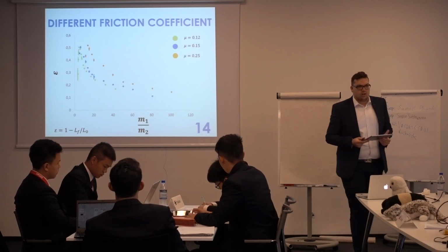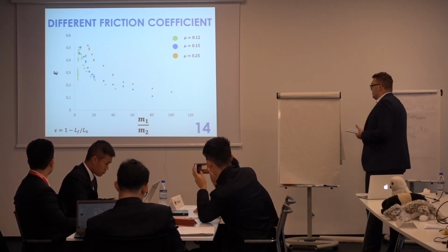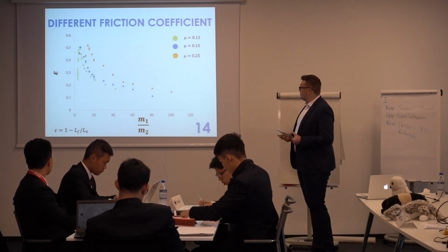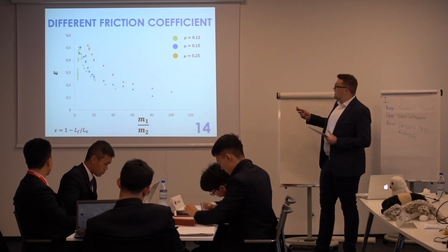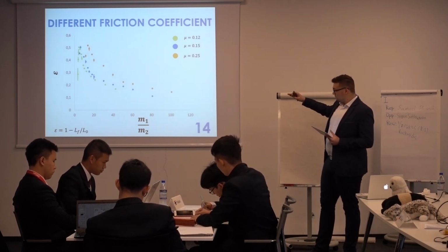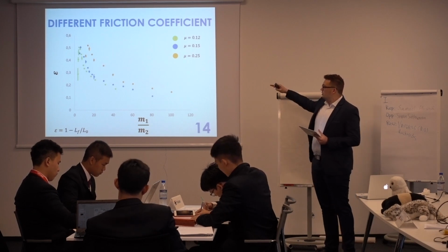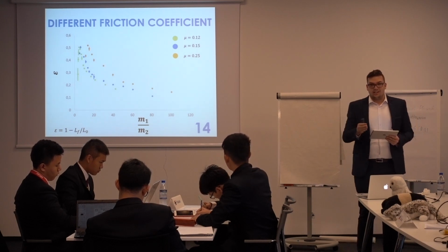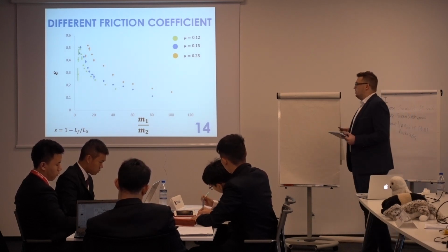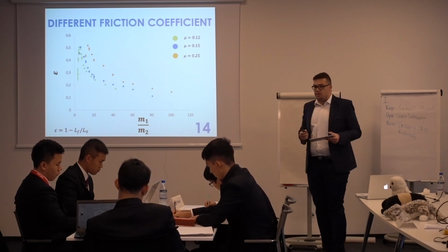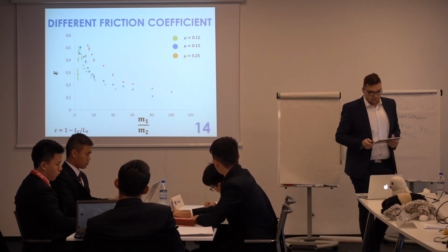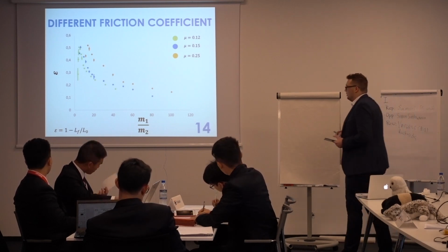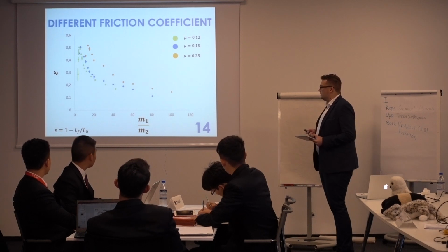So, next, we change the friction coefficient of our rod. We can see that with greater friction, as the orange dots are the friction, we are pushed upwards in the relative turn. This is because with greater friction, less turn is needed for the load to stop, and therefore the rest of the thread itself swings around the rod and we have a greater relative turn.